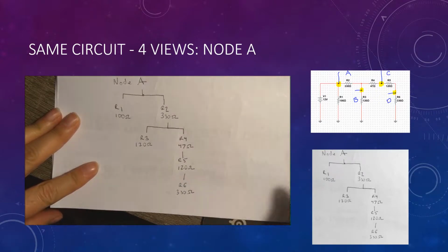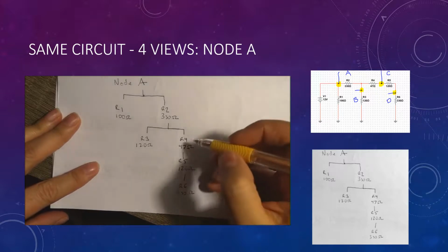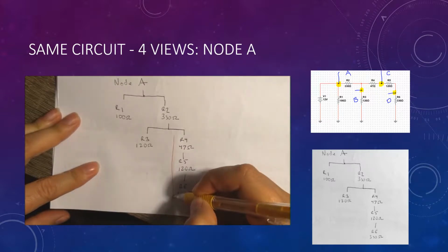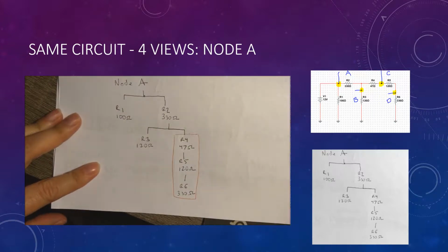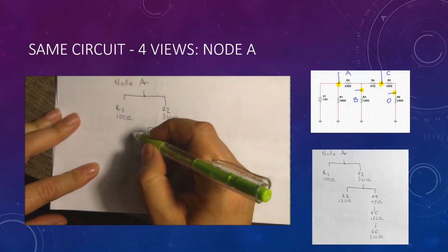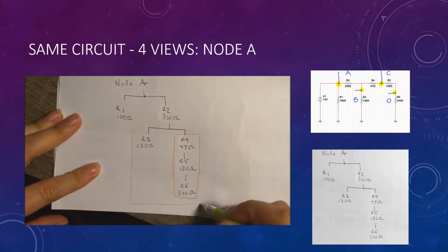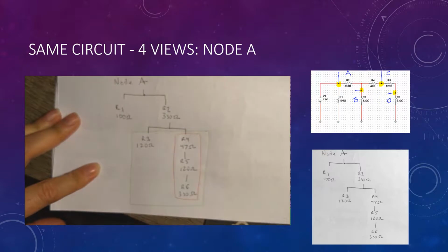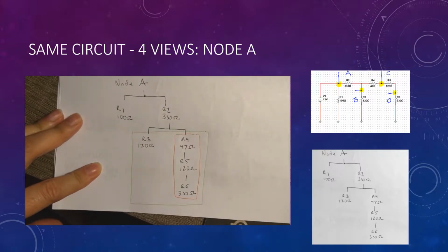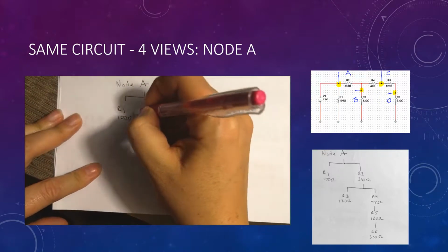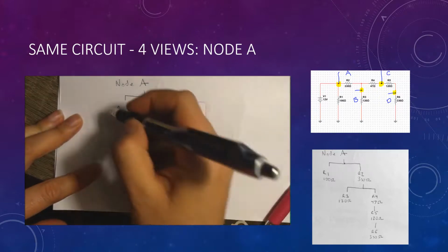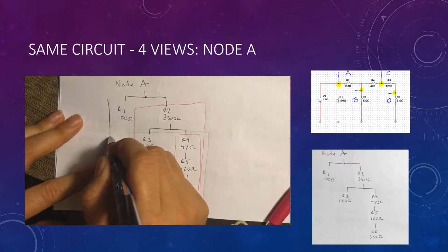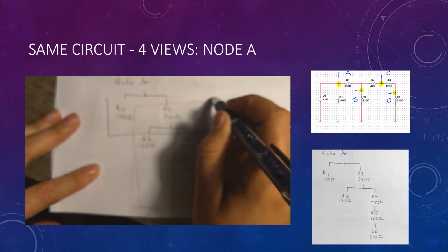From this, we can now work on solving the resistance by pulling out the types. As we can see, R4, R5, and R6 are in series. We will then evaluate R3 in parallel with that result, then R2 in series with the resulting value, and R1 with the previous result as a parallel. In our next slide, we'll go over the mathematical equations in solving this.